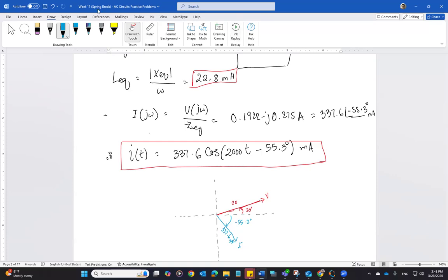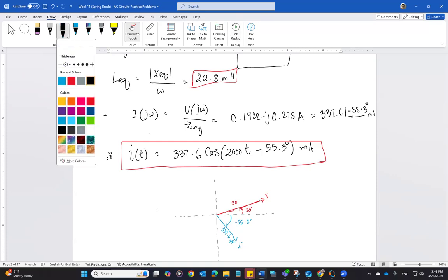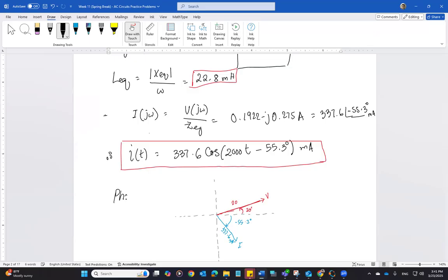So that's a phasor diagram of the circuit, and you can draw the phasor diagram between any current value and any voltage, or between different voltages. A phasor diagram is a representation of quantities in polar form on the complex plane, represented by their magnitude and phase. So it shows how different quantities are related as far as if they're lagging each other, if they're leading each other, and what is the magnitude of each quantity.